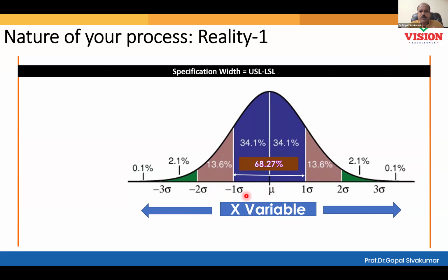And now what happened? The process has got shifted. Can you see that? Maybe for some reason you need to find out. But still, the problem is not getting elevated up to the end user. Even though the process is shifted, still everything is well inside the specification. However, you don't have to wait till your process and the products go beyond the spec. The moment you understand there is a shift, can't you pull back the process? If you pull back, what is the advantage?